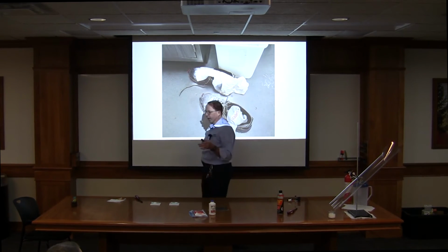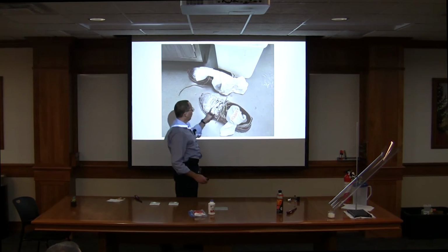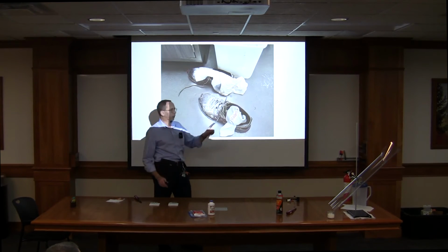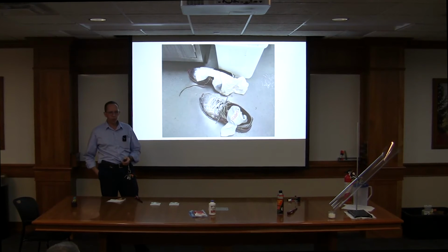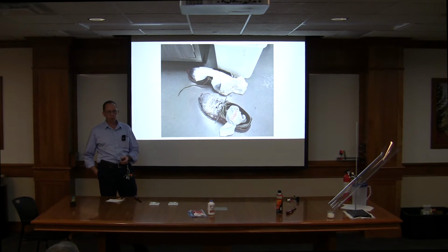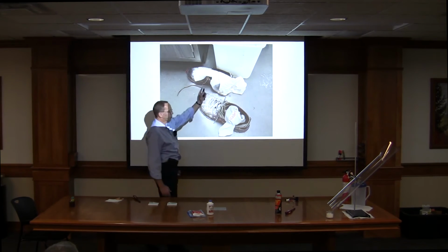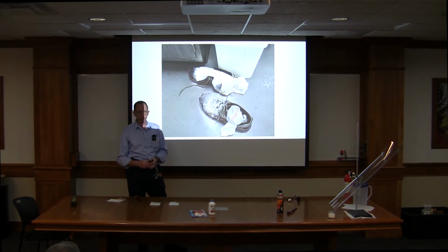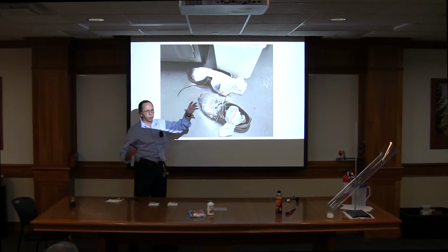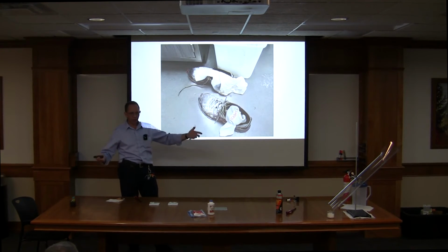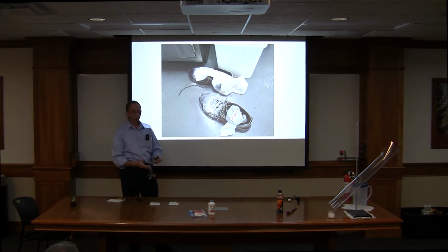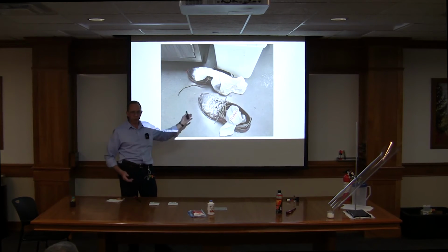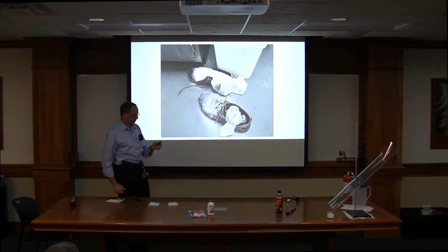Now, how long do you think it took for the sulfuric acid to go right through that mesh and start chewing the top of his toes? It didn't even slow down. As soon as that thing dropped, he reported that he felt it gnawing on the top of his feet. So you can't even kick your shoes and get your socks off fast enough before you start having damage. So, a plug for PPE here. If you're working with these highly corrosive materials, at a minimum have some good solid leather shoes, preferably have some rubber boots that are impervious to the liquid, but make sure you keep that stuff off you.